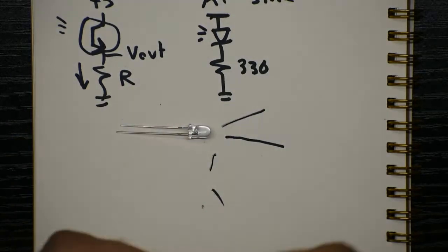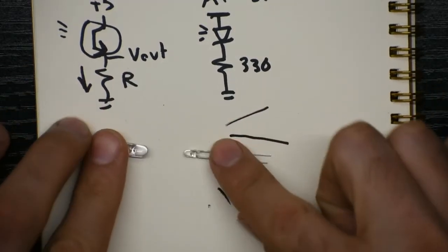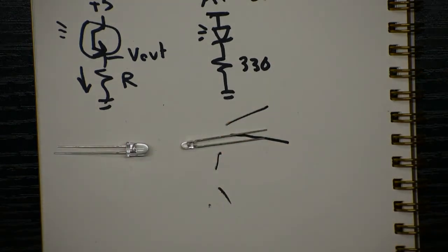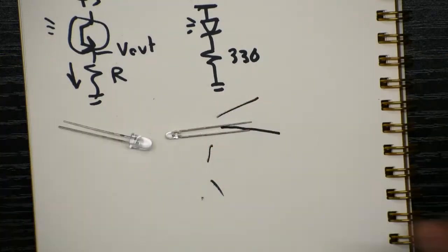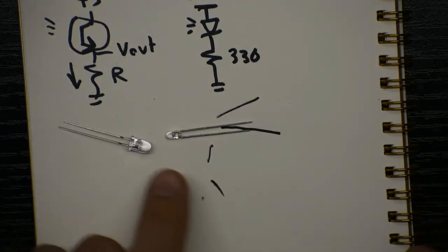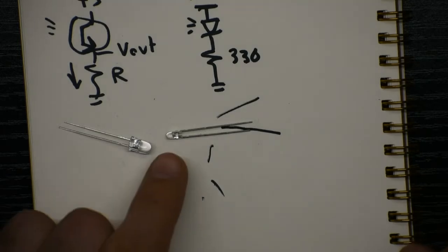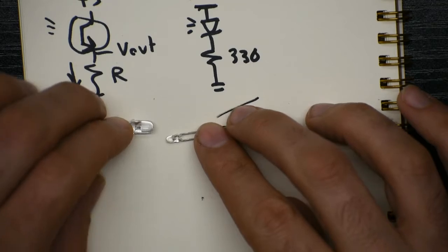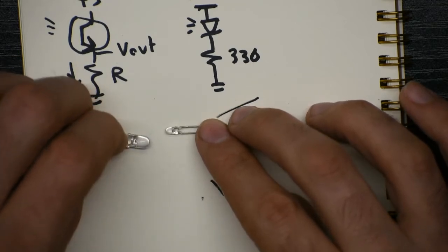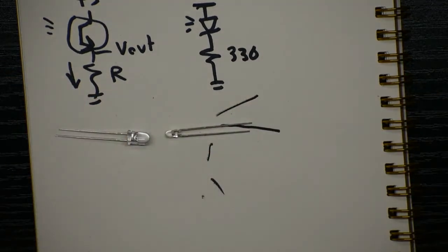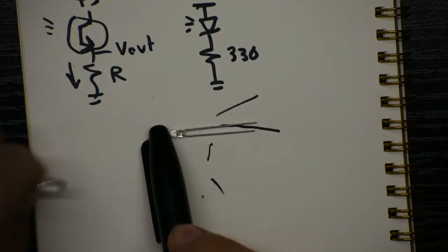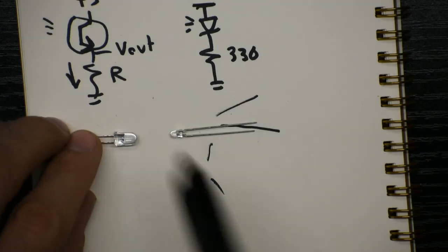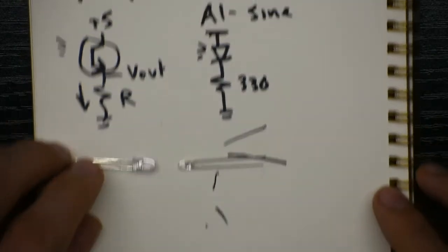And what we're going to do is build a circuit so that they're about an inch apart. So the light comes out of the LED and goes into the phototransistor. And if they're not aligned very well, so if they're pointed like that, not much light is going to come out of the LED and hit the phototransistor because of those lenses. So we'll have the ability to adjust how well this works by aligning them, as well as if you just put something in between them, right? That would block the path of light. If it was like tissue paper, then some light could still get through, but we can also block it 100%. So that's the circuit we're going to build right now.